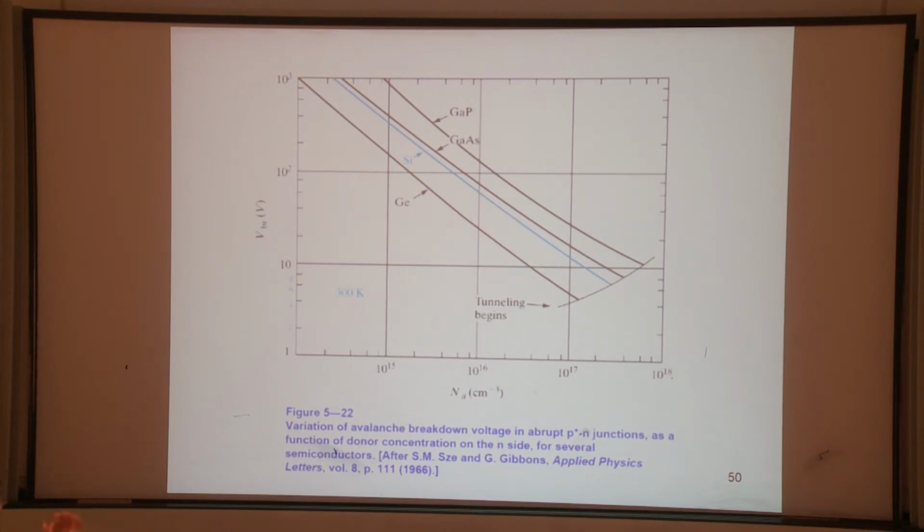But actually it's very low because you need to compare with the crystal structure. Usually in a crystal, in a volume of a centimeter cube, there will be 10 to the 21 or 22 atoms. So 15 compared with 22 is a very small amount. Like you only have 1 dopant in millions of atoms, right? So you only replace 1 silicon atom by phosphorus in millions of silicon atoms. So actually the doping is very low. Okay? Just to show you an idea.